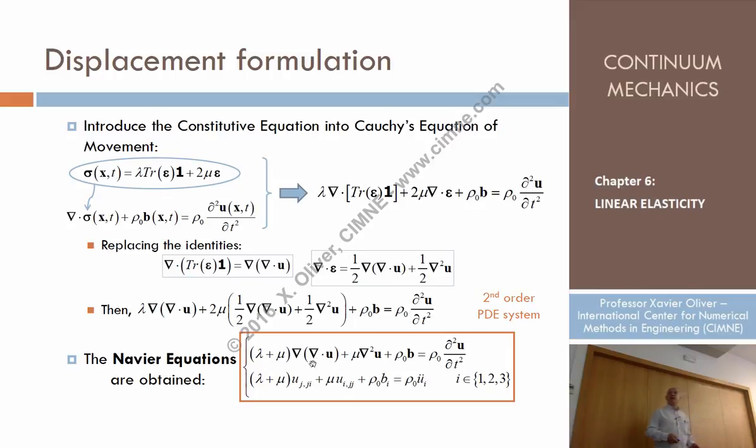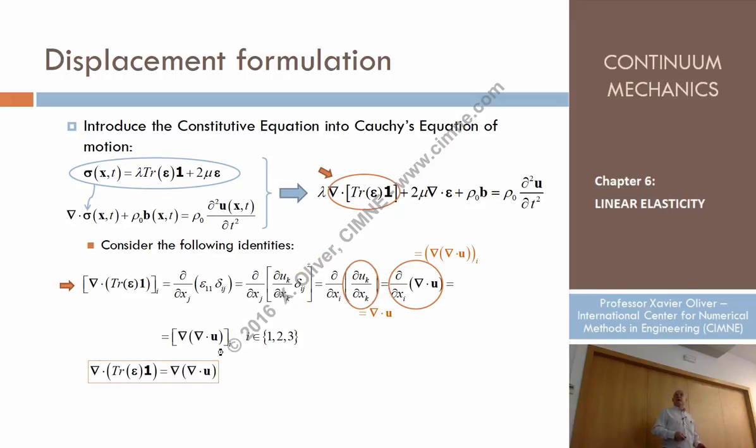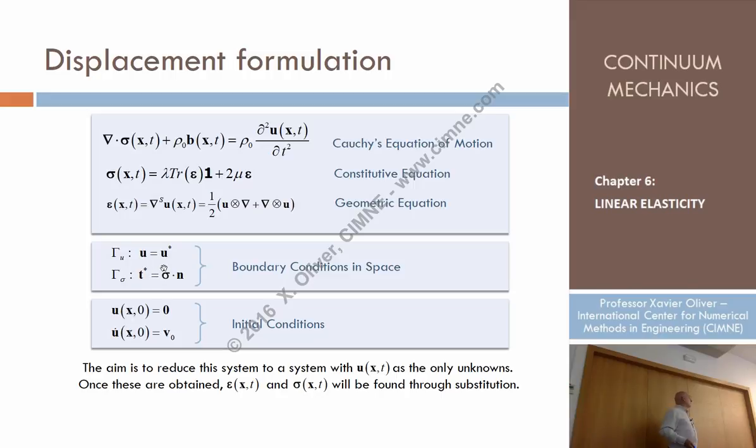So how do we solve the integration constants? Well, we have for them the boundary conditions. Look, the boundary conditions are expressed in terms of the displacements here, but this one is expressed in terms of the stresses. So since now they're unknown, we have reduced our problem to solve a problem in a space in 3 dimensions, in terms of just 3 unknowns, the 3 components of the displacements.